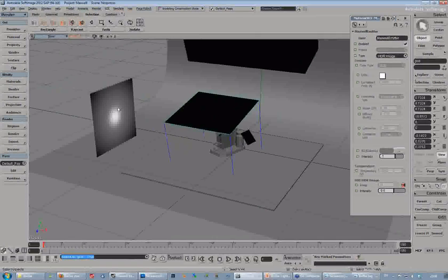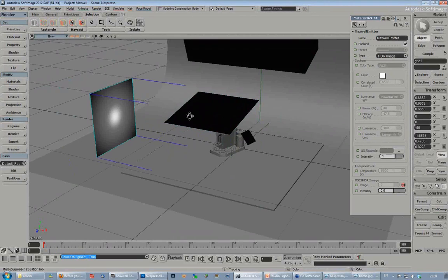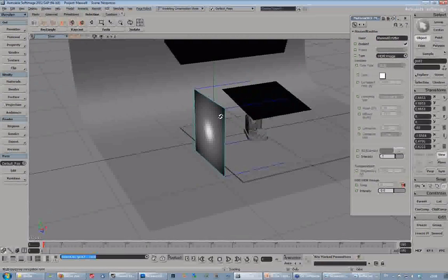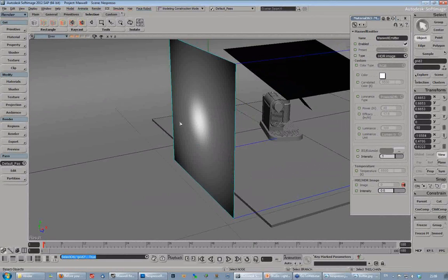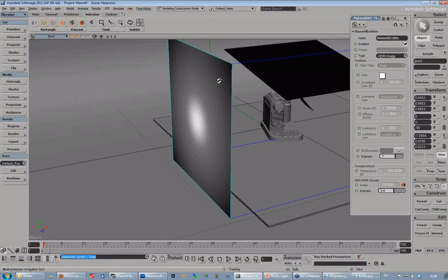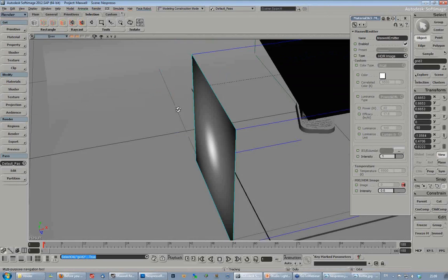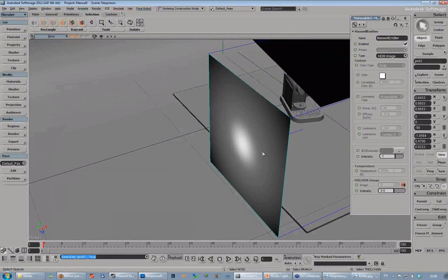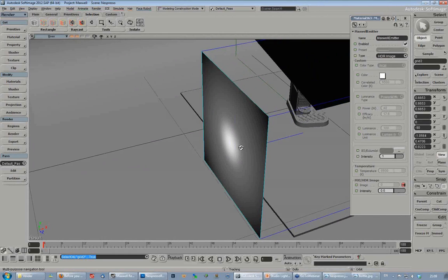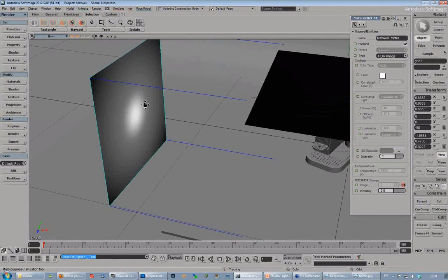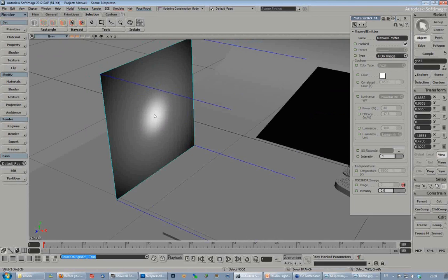No, I try to avoid that because it adds a lot to the render time. Of course you can do it really realistically, and I can place a small emitter here on this side and set this plane so it needs a thickness if I want to use subsurface scattering, or thin SSS. In that case, it doesn't need a thickness, and you're going to get a realistic effect. But it can add a lot to the render time if you do that, especially with volumetric SSS. So I just usually fake it using these HDR images. It's sort of the same effect, basically.